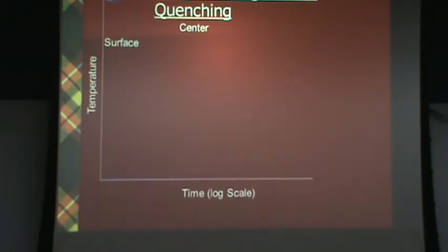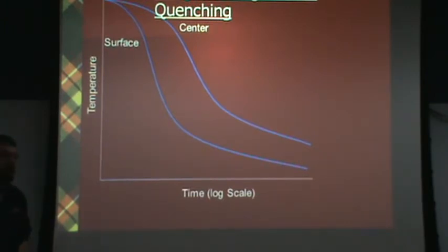Rough turning means that we're machining that part in advance of quenching. The reason for doing that would be to reduce mass, but also to remove the oxide layer. You saw in the picture of that big funnel-shaped part a minute ago, we had a lot of oxide on that part. That's normal from forging. Well, that oxide layer is an insulator. So if I want to enhance the cooling rate, speed it up, I have to get rid of that insulating layer. So I would machine that off.